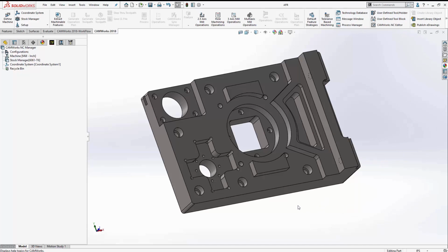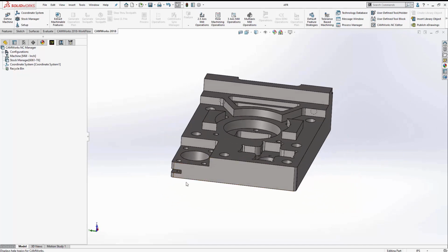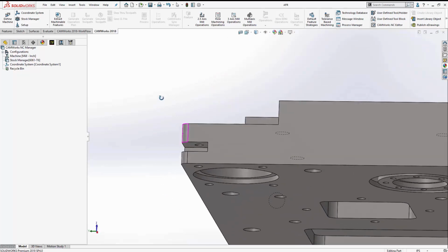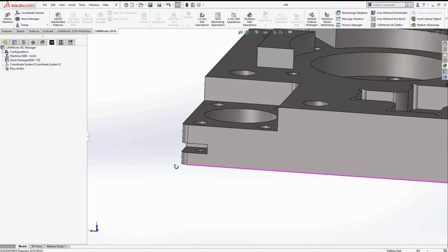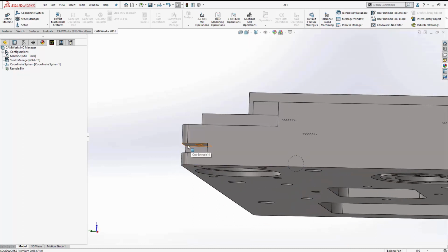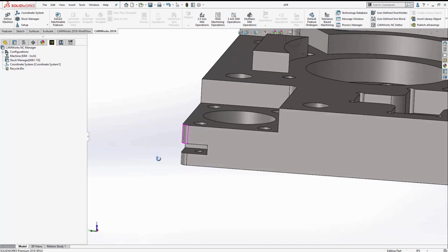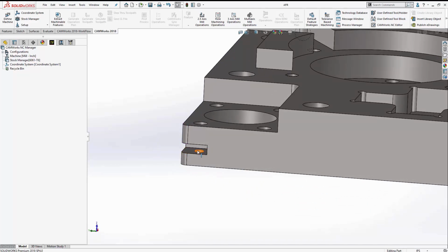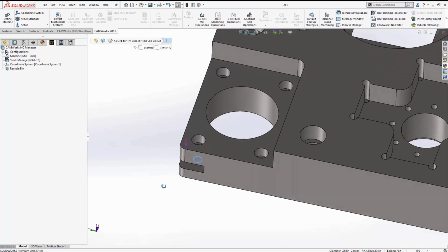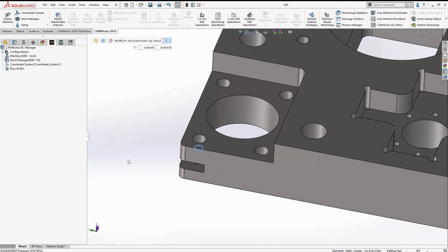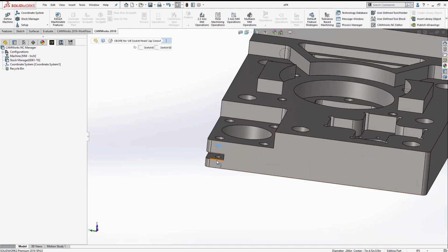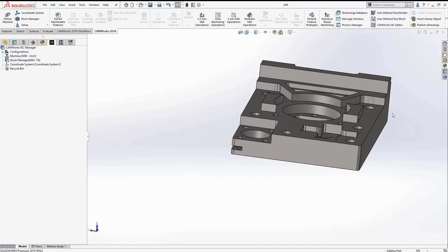And let's talk about condensed split holes for a second. Here's the example of what that's referencing. It's referencing when you have technically one hole feature, but it's split between a cut extrusion. If we don't have the condensed split holes checked, it's going to see these as two different hole features rather than one. So it's probably wise to keep that selected so that it doesn't try and create two holes for the same hole.